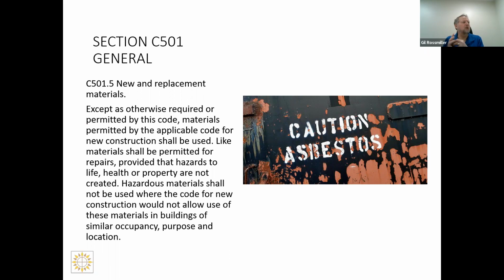For example, is removal and replacement of the interior drywall alone altering the wall assembly, or does that wall assembly need to be brought to code? Absolutely not. Generally speaking, it gets clearer and clearer in our coming codes. But if I take the sheetrock off, and there's insulation in that wall, we're done. Move on with life.